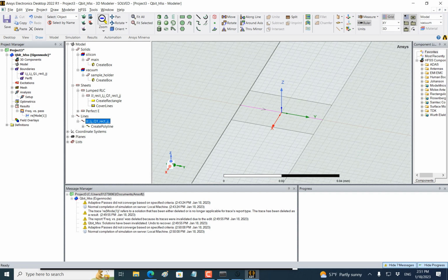I say that the whole Josephson junction is just modeled as a conductive plate, because we don't simulate the detail, and we cannot do that in HFSS. What we care about is that it gives us a very large inductance, which is 10 nanohenry, as we showed earlier. But we need to have this line because it is going to find the energy by integrating along this line. So this line does not affect the simulation.